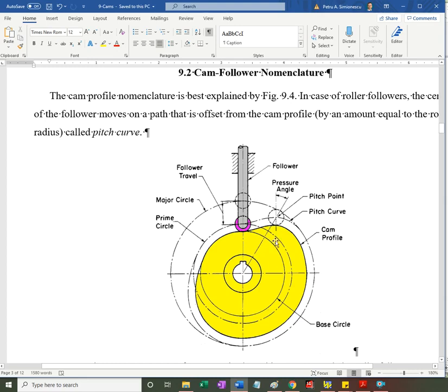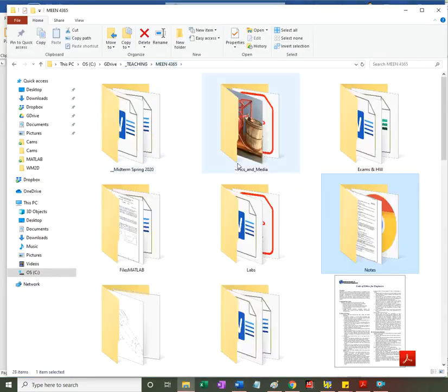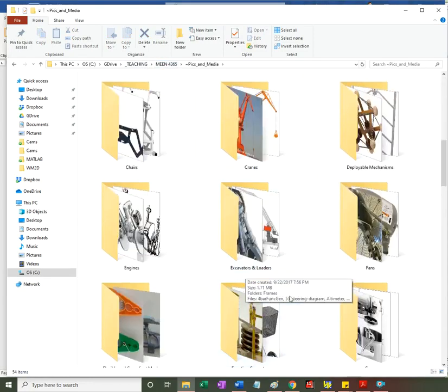If it's spring loaded, then you want the acceleration induced by the spring to be enough that contact is maintained. If contact is due to gravity, like in a stamp mill, you don't want the theoretical acceleration of the return to be higher than the acceleration due to gravity, because there will be loss of contact, which actually happens on purpose in stamp mills. Okay, we'll look at those.